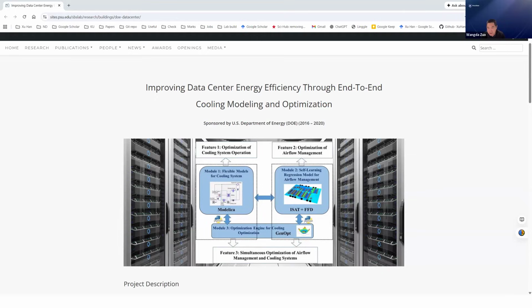I think they're asking about the block we use to calculate the error. Yeah, I think we just built it by ourselves. It can be pretty straightforward. Modelica is an equation-based programming language, so you just define the input, define the output, and put in the equation, and then it can calculate the NMBE based on the input and output the results.